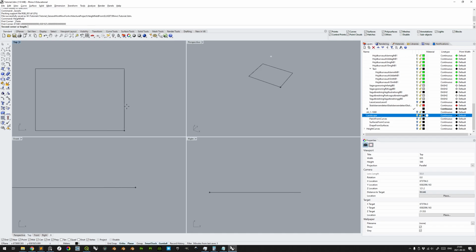If you input the second corner coordinates in a way which Rhino does not expect, or if you have the cursor towards a direction which is not intended, this can lead to some very weird rotations, scalings, and positions of the height field. So it is most reliable to simply input the minimum extents coordinates for x and y, like we previously did, and then to input the length, which is the same as the width of the image resolution, as the image resolution is 1 pixel equaling 1 meter, since this data set has that resolution.